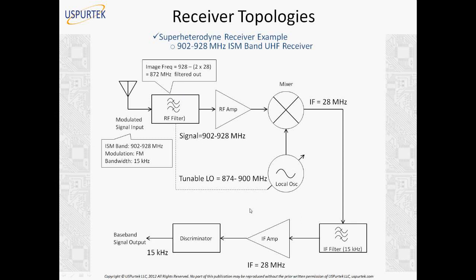So this is very important. Whenever we design the IF stage of a superheterodyne receiver, we have to consider this. We have to consider, are we able to reject image frequencies or not? Because image frequencies can be a nuisance. That will undermine the selectivity of the receiver itself. Instead of selecting one carrier frequency, you are selecting two, if you are not careful, if you are not rejecting the image frequency. So I hope I have clarified this. If any question, you can ask me.